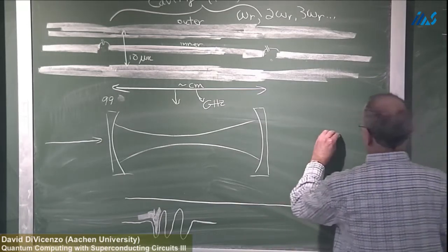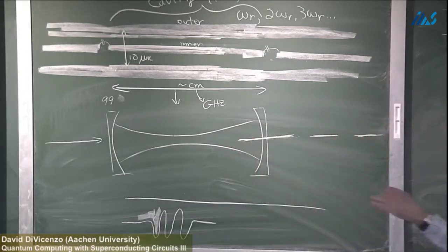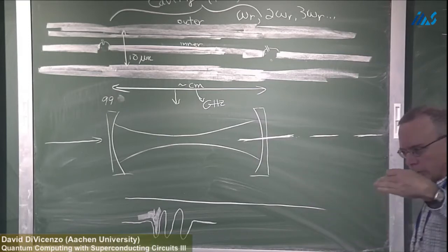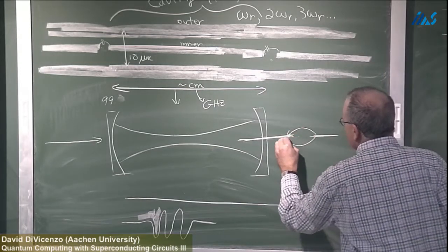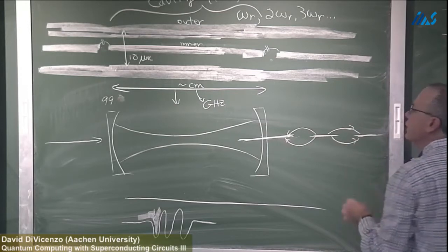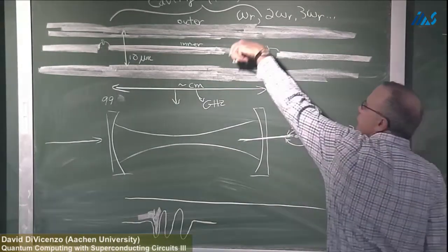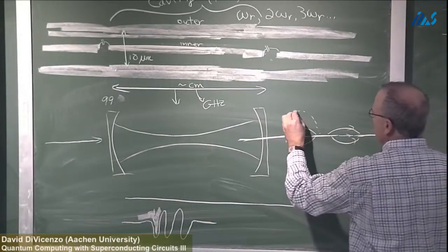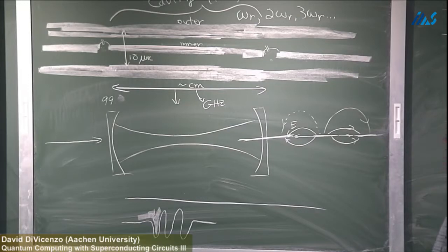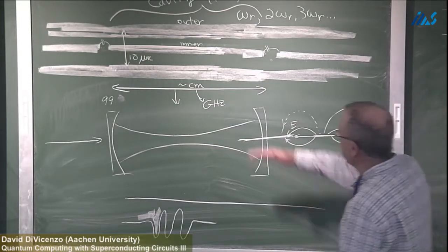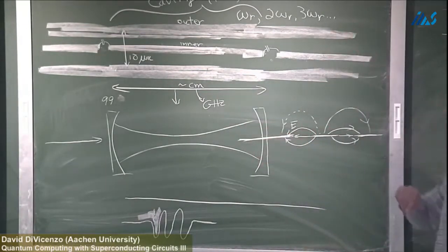So if you look at a cross-section, here's this thin metal, and then a gap, and then the thin metal on the sides. I claim there is, in fact, traveling radiation, guided, confined radiation that goes this way, and the electric fields look something like this for that mode. So it has no simple linear polarization, but it does have a strong concentration of the electric field pattern inside this gap, with really only evanescent, quite weak fields out here. Although I haven't thought that through completely, it probably also has to do with the width of these ground planes. If these are not infinitely wide, then there is some leakage out to free space.